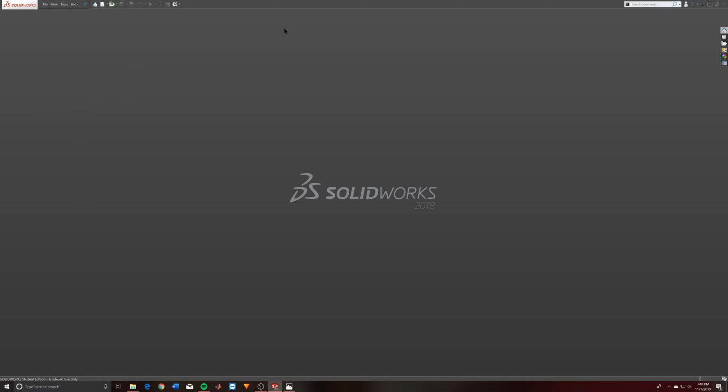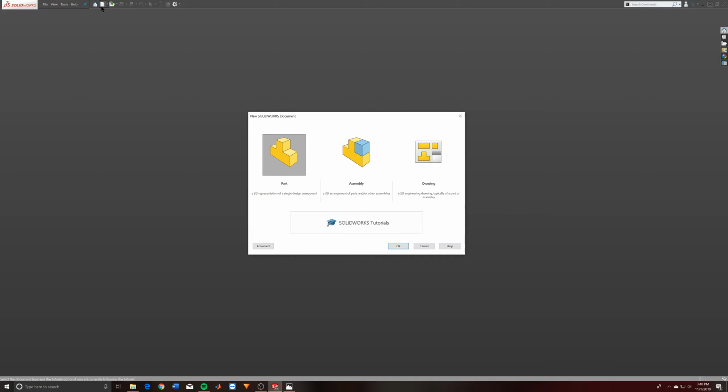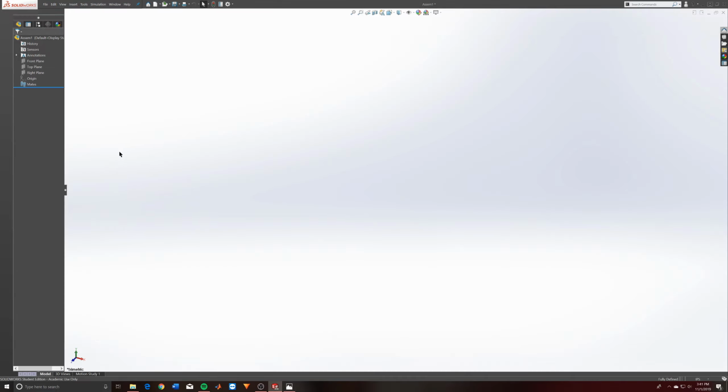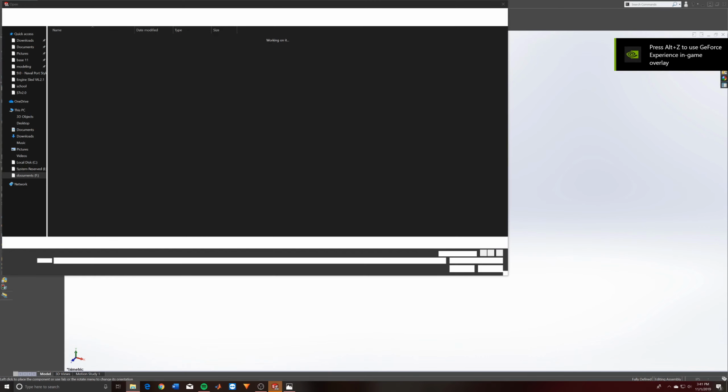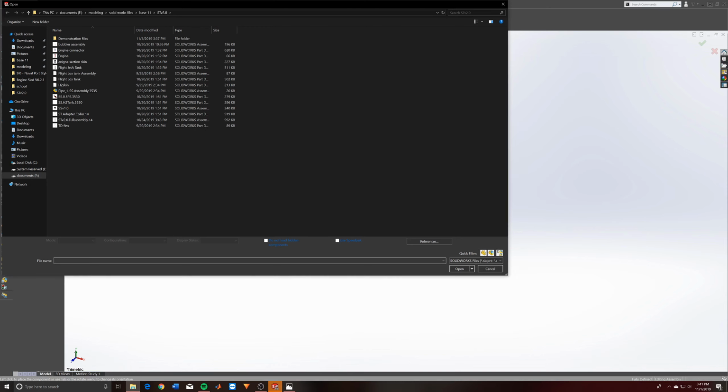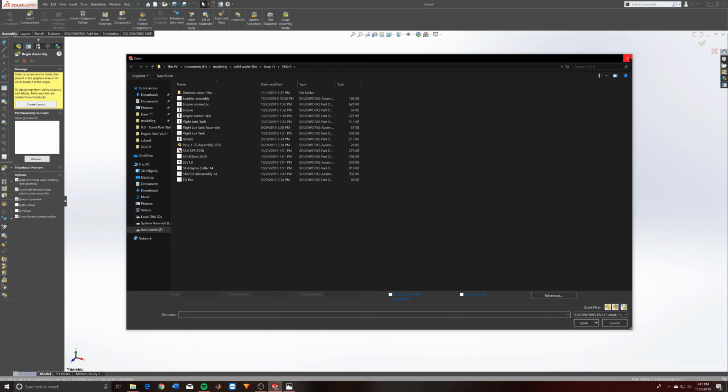So pretty much, first of all, to get started, all we need to do really is open a new assembly, and the main thing to note in difference is that we're going to be operating in a new window. This assembly window here is different than the part, and as you will see, a lot of the toolbars will change up here and down here with different features which are more relevant to actually assembling things together how you want. I'm just going to close that for now.